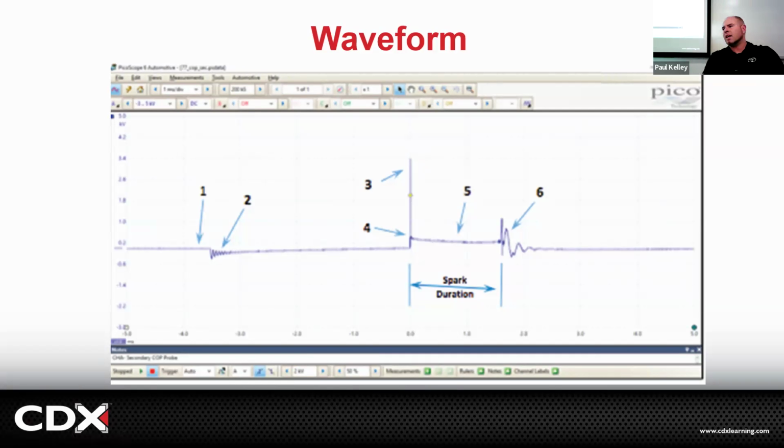Cool. So I remember on A8, there were 4 cylinders graphed, and cylinder number 2 had a really high firing line, and it was trying to say, like, what's wrong? You know, is it an injector? Is it low compression? Is it, you know, maybe low secondary voltage, or like a chewed wire to the primary?